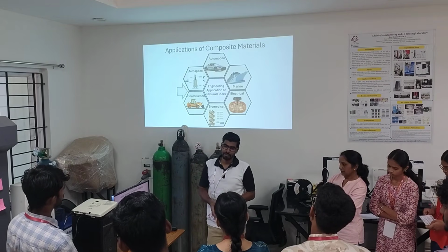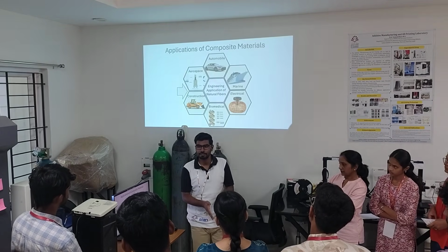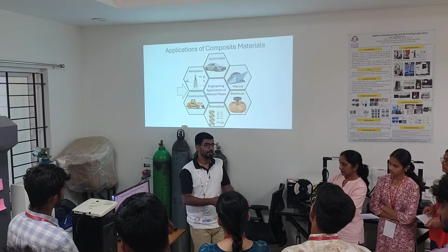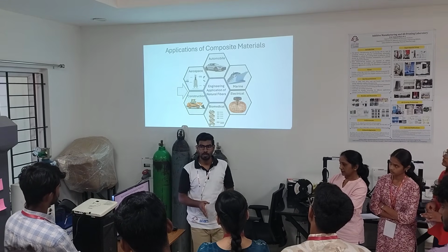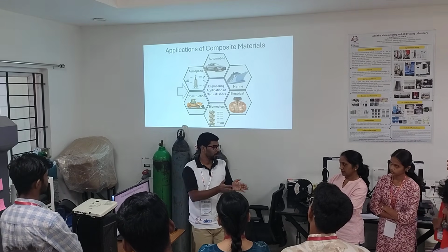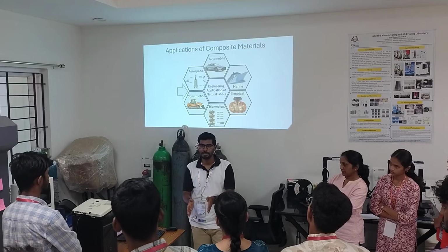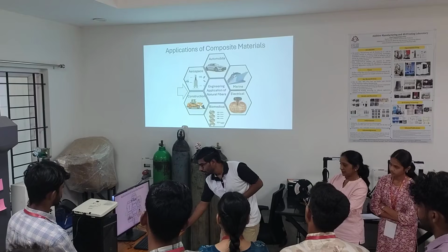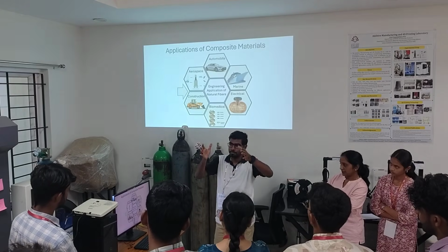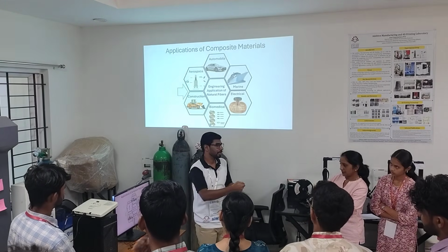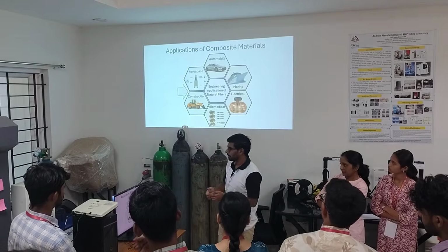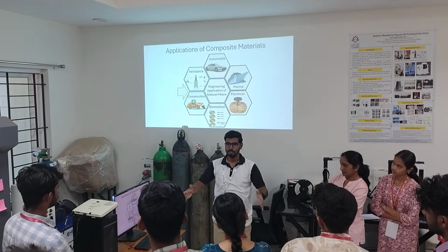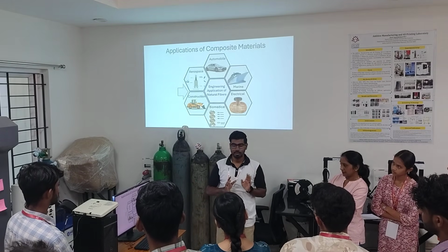Later on, while I was there for 1 year, it was proposed: why can't we go for CFRP? Now half of them are made with aluminium 2024 and half of them are made with CFRP, carbon fiber reinforced plastics. Before, different panels were riveted together, but now it is a single whole body of CFRP.